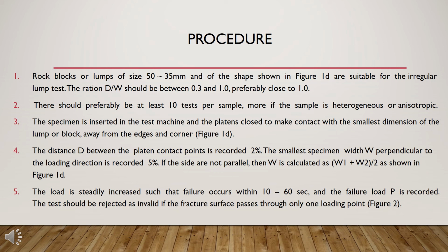Fifth, the load is steadily increased such that failure occurs within 10 to 60 seconds, and the failure load P is recorded. The test should be rejected as invalid if the fracture surface passes through only one loading point. Figure 2.